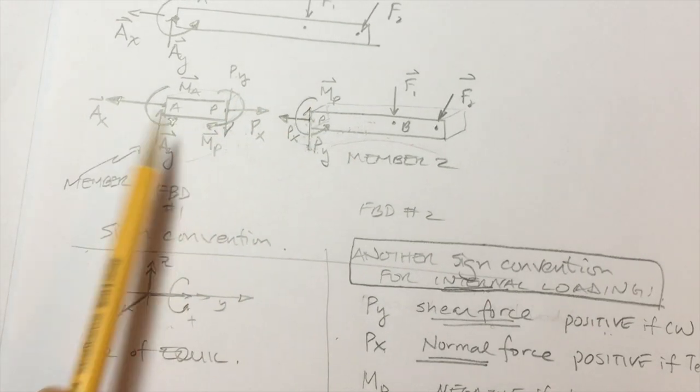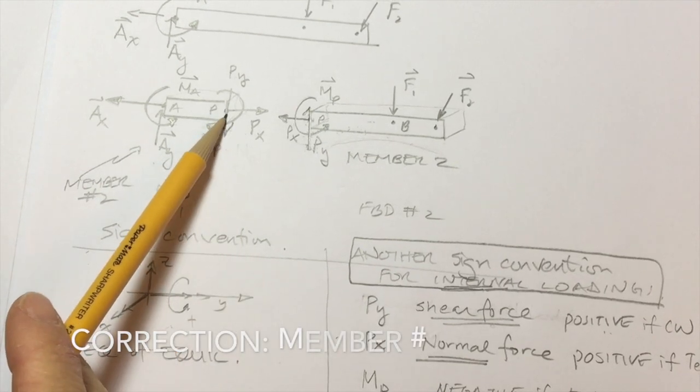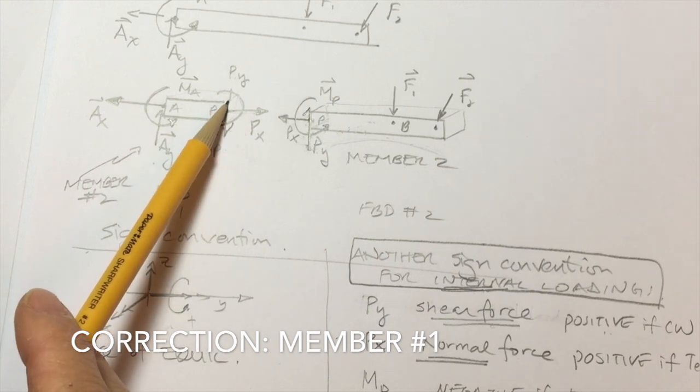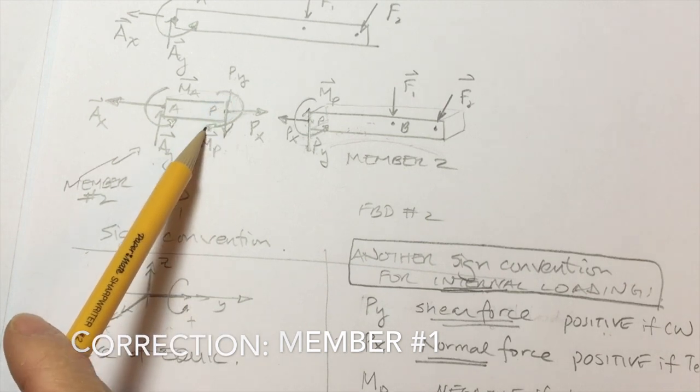If I'm talking to you about member number 1, then I'll say that the internal loadings at P have a positive normal force, a positive shear force, and a negative moment.